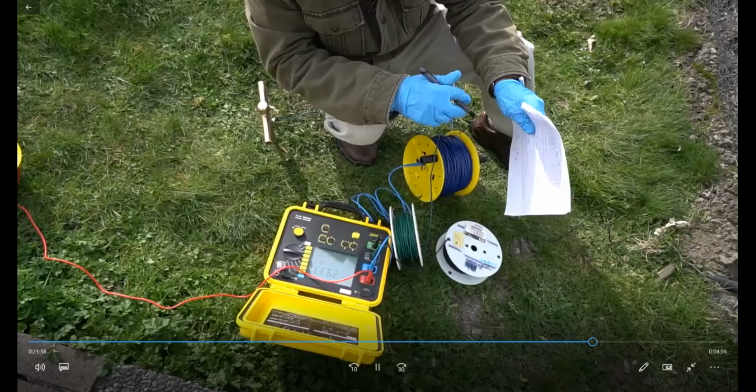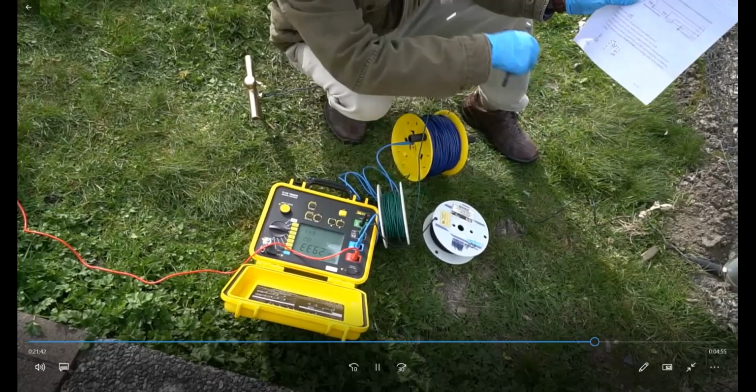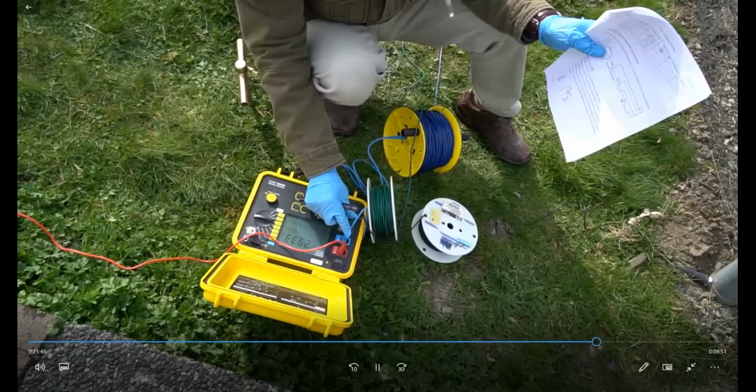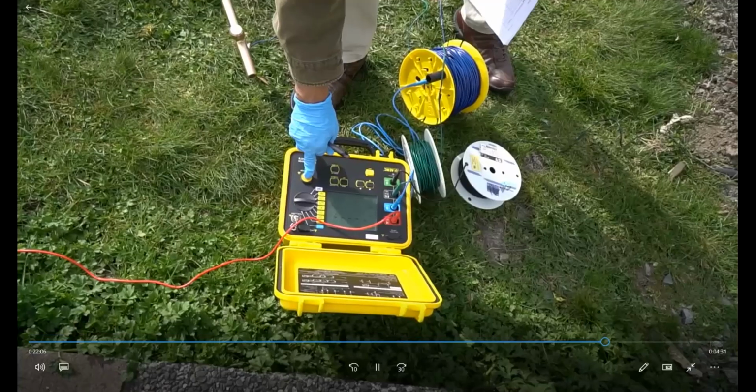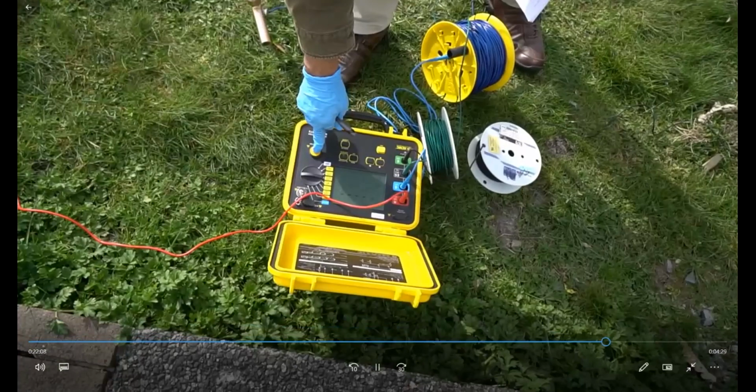In the previous one, this ES was connected with this ground together, it was a jumper together, but now we have to use these 2 probes in order to measure the resistance between 2 legs representing these 2 probes. Okay, so they're set up 1 meter away from each other. There is 1 probe and there is 1 probe. Now our meter is also set up. We'll just press the start button and we'll see what the resistance is here.